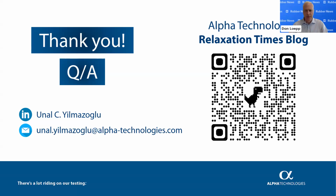Okay, lots of questions. Keep them coming. Is it possible to correlate MDR or Mooney with RPA? I will say MDR is the grandfather of the RPA. In MDR, you are using an isothermal cure, the only capability of an MDR. So you don't need to do any correlation. You can run exactly the same test with an RPA. And with the RPA, yes, you can have a really good RPA Mooney correlation, ML1+4, ML1+8, etc.